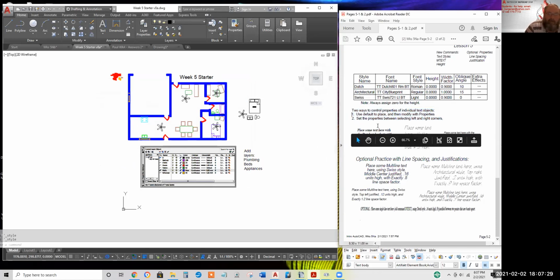Anyway, some of the properties of text you can select in the process of creating it. And I highly recommend you set the height while you're in the process of defining the right and left margins. I'm tempted to say everything else, go back later and tweak in the properties dialog box. Again, it's tempting to go up here to the Microsoft Word looking toolbar, but I think that kind of butchers and de-standardizes, deviates from the everything by layer concept.